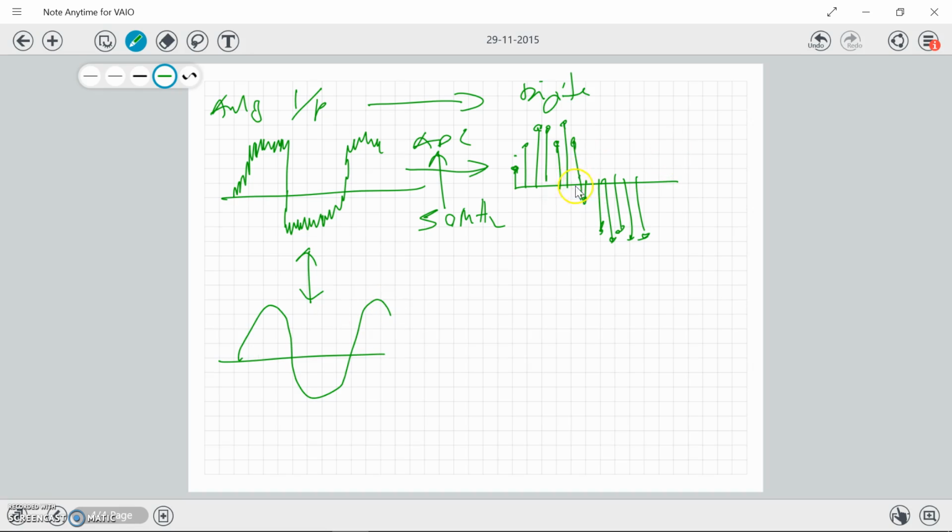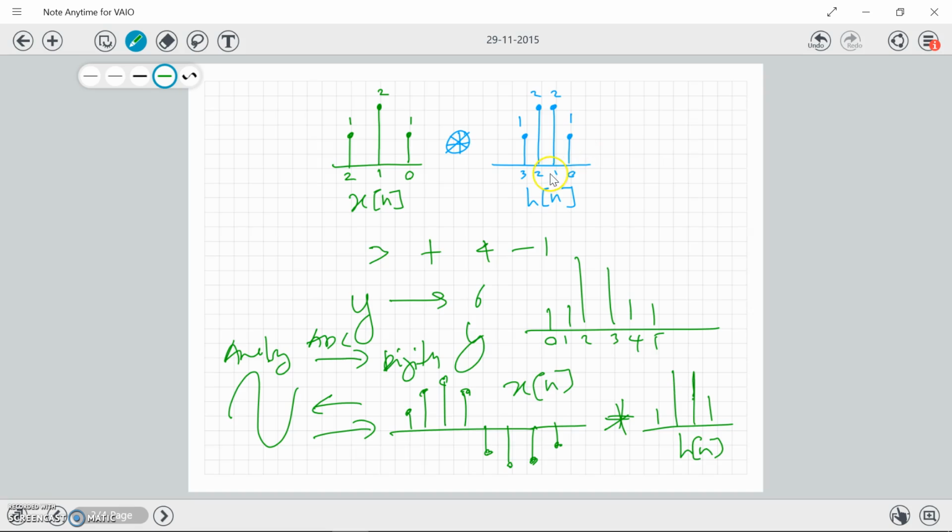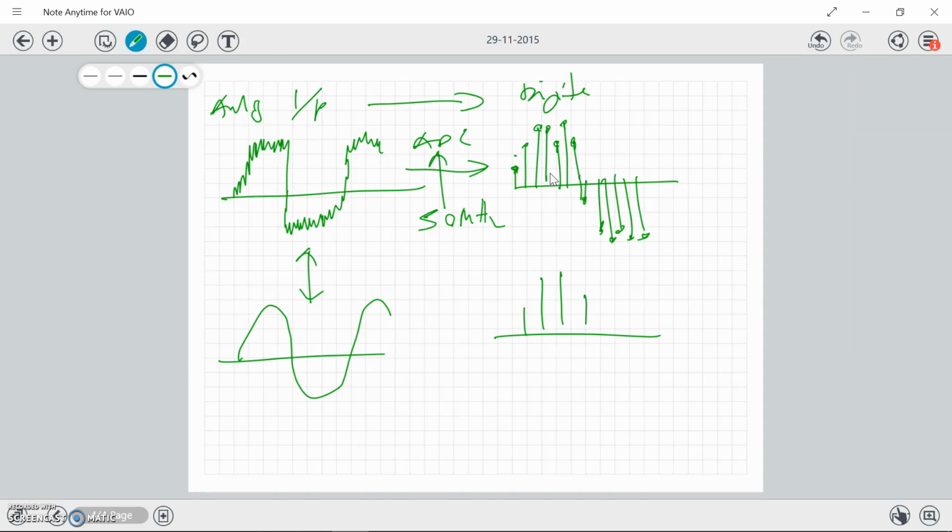Okay, so that's why you must apply a filter. This is our filter from just now, the blue color here, our filter impulse response. So you're going to do the convolution. Whatever this signal here, you're going to convolve with this signal. So you're going to get a smooth impulse, which represents the pure sinusoidal signal here. Okay, I think you already get the idea of the overall reason why we are doing all this.